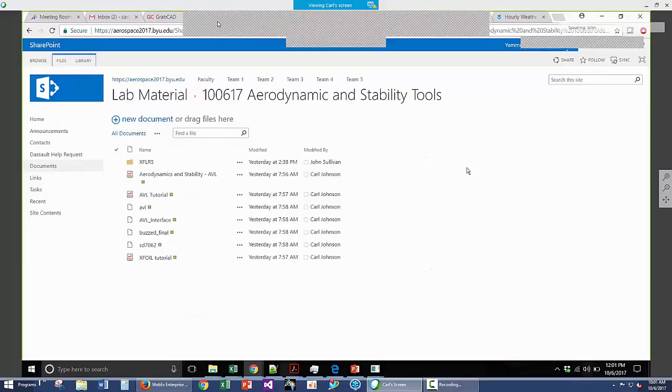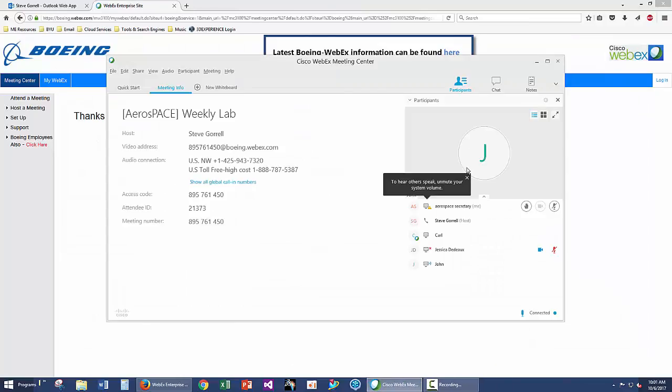There is one other website that we find useful. It's called Airfoil Tools. What Airfoil Tools does, it's got most of the Selig airfoils, and it has Xfoil calculations for all of them. So it's a good way to get a survey of the type of airfoils you might want to look at. After you look at that, you're going to have to go and run Xfoil and some sort of a wing analysis to go with it. But it's a good way to look at an awful lot of calculations quickly.